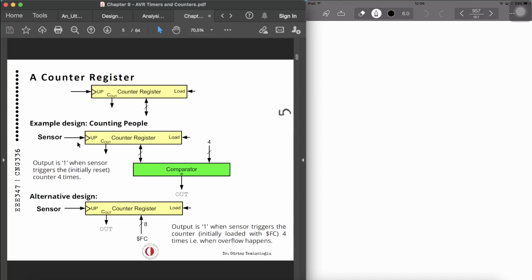And as a result of this, the counter register represents how many ticks have occurred from the time we have cleared the counter. And as we know the speed of the oscillator in the microcontroller, we can easily calculate the tick period from the content of the counter register, and we will know how much time has elapsed.